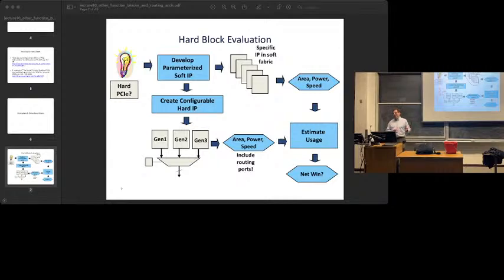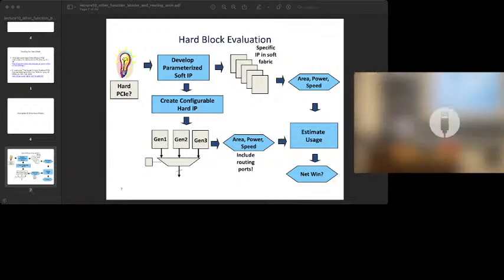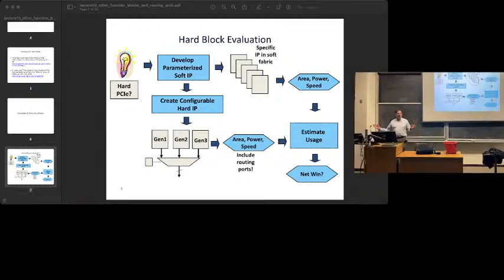And this allows me to cut off their leakage power. And I don't clock them when I don't use them, so they also aren't going to take dynamic power. So the increasing importance of power makes you want to harden more stuff, as long as you put these sleep transistors on it so that it doesn't leak when you don't need it. Does that make sense? You still have to pay attention to area, though, so that doesn't mean you just go harden everything you want, because your cost will be terrible.